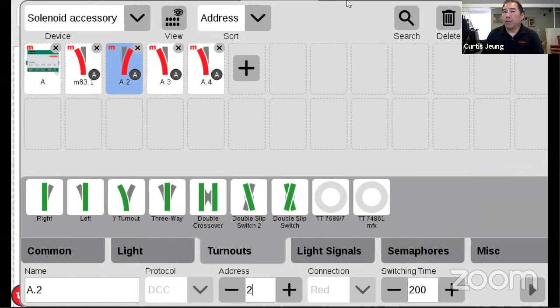If you delete that locomotive from your inventory, but you pulled the locomotive off the track first, then when you delete the locomotive out of the CS3, you're only deleting half the handshake, because the decoder on the locomotive still thinks it's paired to the CS3 that you had registered it with.